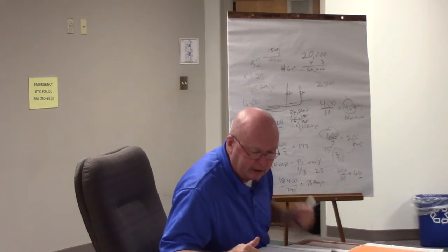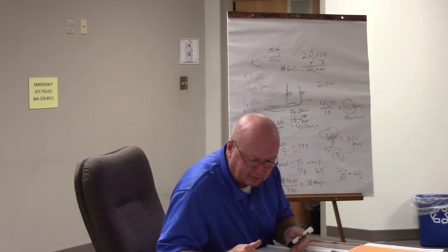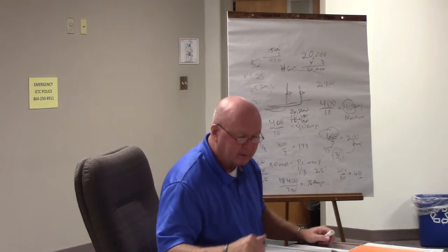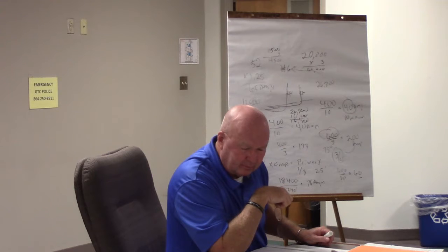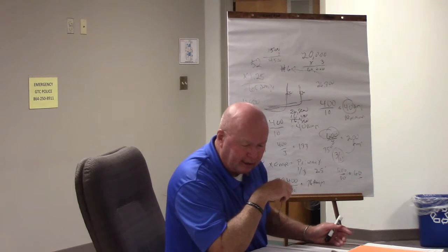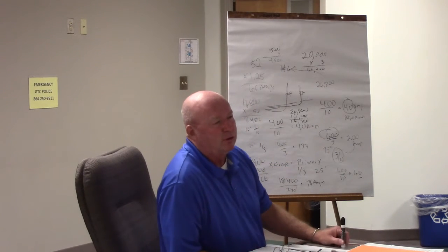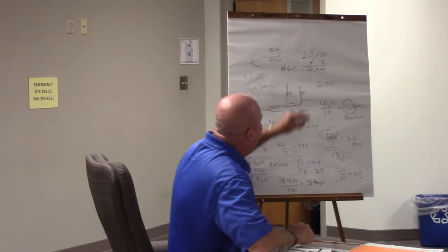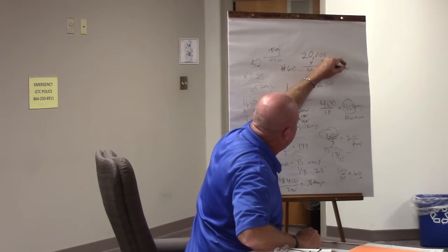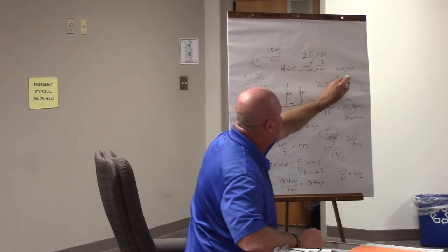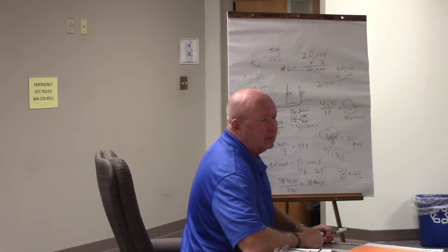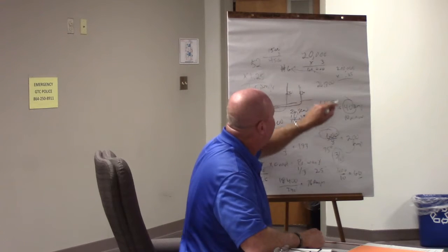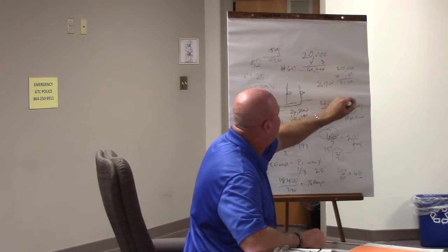We don't do dwellings, but we do a restaurant. What is a restaurant per square foot? Restaurant is 2. Now look at something that we really do a lot of, a storage warehouse. How much for a storage warehouse? A quarter. Pretty small, isn't it? So we have a 200,000 square foot warehouse. What are we going to multiply it by? A quarter, 0.25. So 200,000 times 0.25, what is the lighting load? 50,000. Less than James's house.